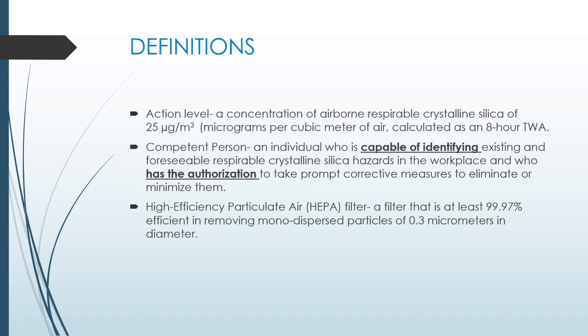So definitions. You're going to hear a couple of these words throughout not only the silica program, but throughout construction standards as a whole. What is an action level? An action level, when it regards to silica, is the concentration at which the employer has to do something. Believe it or not, you can be exposed to a certain amount of things and nothing's going to happen. No one has to protect you from it because it's a negligible amount.